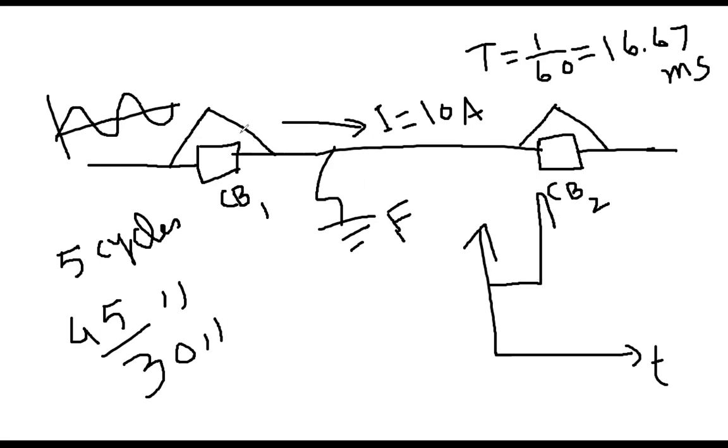So at the next attempt, what will happen? Because you closed, the current may go much higher. And then again, on the third attempt, it may go much higher. So what is the issue with that? On one hand, it's a huge burden on these lines. These lines may fail, but even these circuit breakers have some withstanding capability. They may not tolerate this amount of higher and higher current. You understand? Therefore, these circuit breakers might even be damaged.